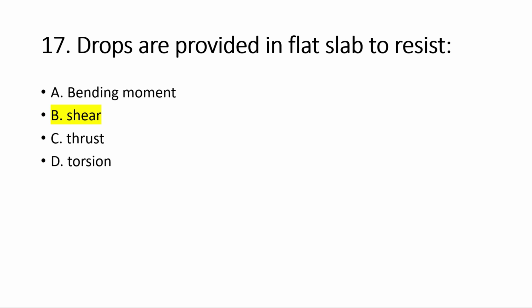Drops are provided in flat slab to resist... Okay, so this is an important question, and drops are provided to resist shear. We know drops increase the shear strength of the flat slab floor, and also drop panels increase the slab's negative moment capacity. So drops are provided here to resist shear only. And here the drop panels also reduce the deflection by stiffening the flat slabs. So option B is correct. Okay, move on to the next question.